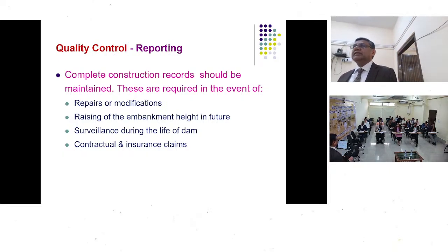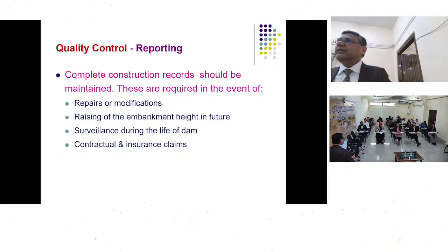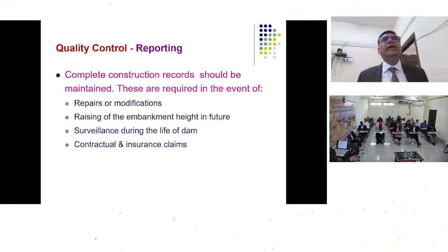You will say, okay, we have constructed a good dam, it is functioning fine. Now what is the requirement of all these documents? The work was good, everybody was satisfied. Suppose it is a dam with power production. Power production is also up to the mark, and water storage is also there. Seepages are very nil within the limited quantities. The deformation of dam is within the 1% or 2%, whatever we have decided. So what is the requirement? So it is required in case of modifications or repairs.